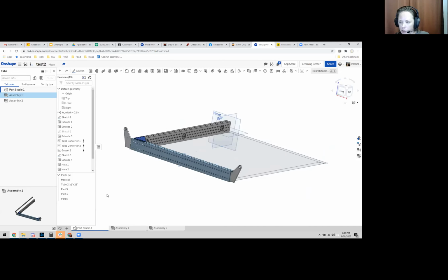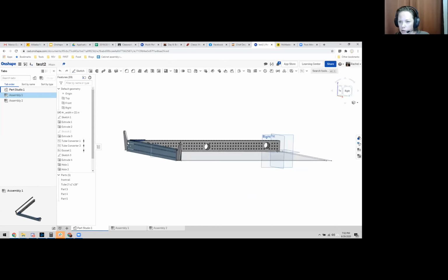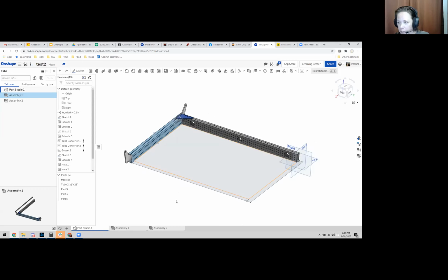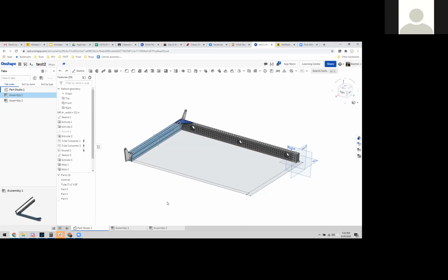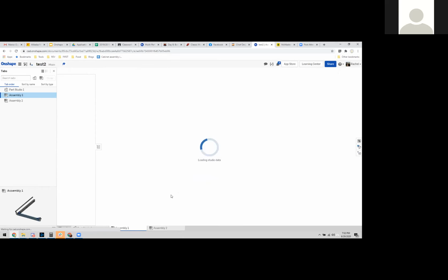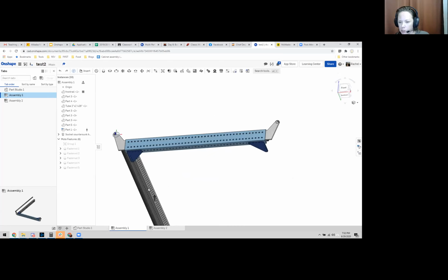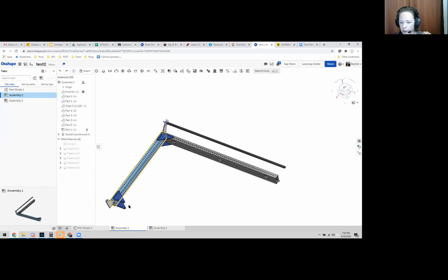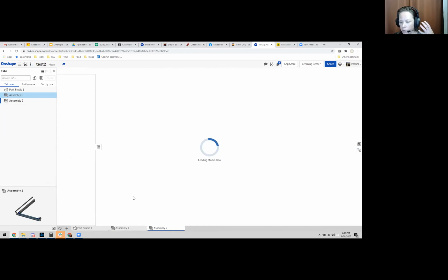But now you have, assuming your front and back rails are identical, this is your part studio. And then I don't have a bracket on the bottom here because I already have the bracket designed on top. But to Ricky's point, I could paste in all the brackets here, and then I would only need to do 2 different assemblies. But here I've done a midpoint assembly. Alan, I think this is what you were talking about, not having the ability to mirror your drivetrain as a frustration in Onshape. This is the way they presented how to do that: you build half of it, and then your assembly is both of those stuck together, right? So I really only have to maintain half of this.